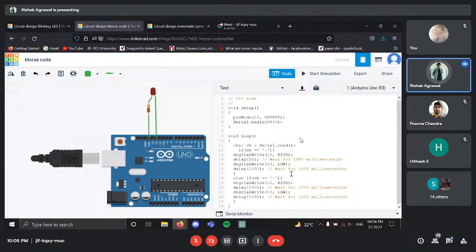You guys can just look into some other projects if you want to see how baud rate changes the requirements. That should be good enough, I guess. So serial.begin(9600) would be the initializing line in the void setup.